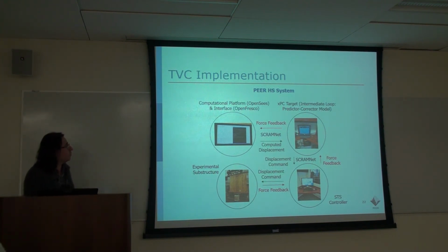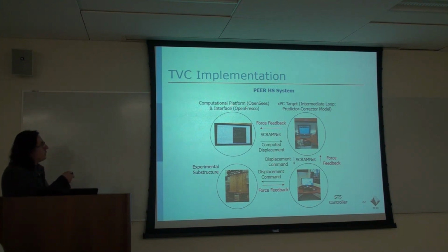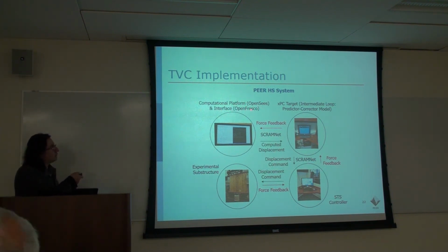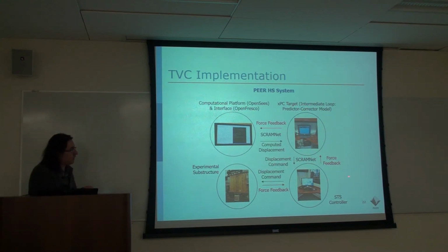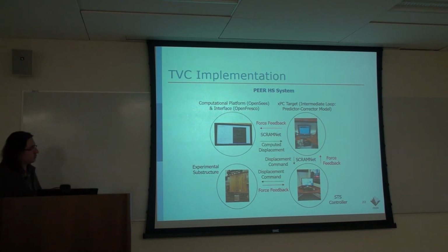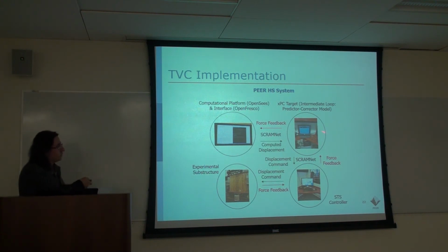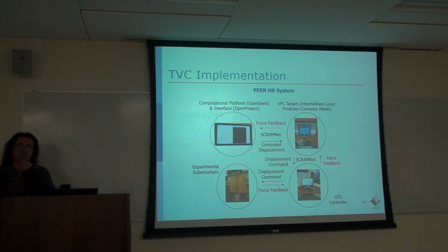Just to quickly go over it one more time: we have the computational platform, OpenSees generally, but it can be anything, plus OpenFresco, and then we have this simulation real-time target machine which runs in real time, and that communicates with the controller, and the controller talks to any actuator in the lab. This goes in this order for displacements and in the reverse order for the forces. So this is the existing hybrid simulation system before any TVC implementation.